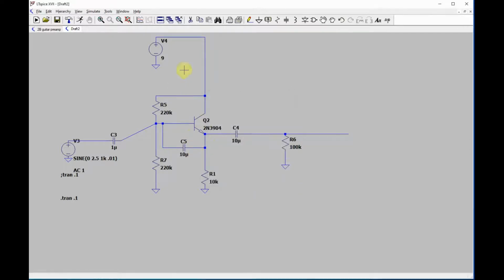Now we're going to disconnect this from here, and we're going to put a resistor here, like 10K or something like that. And then instead of hooking this up to this node here, we're going to skip that whole node. Sorry, maybe not the best. We're going to go straight to the base. Now, it's a couple extra parts. They're passive, but it's kind of neat.